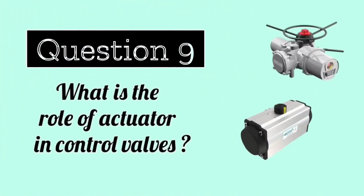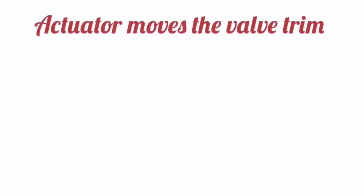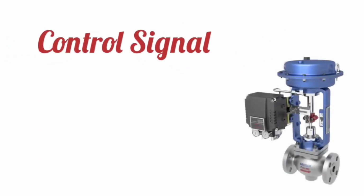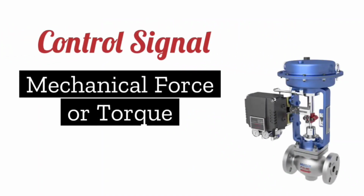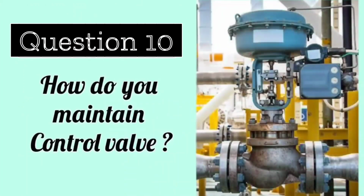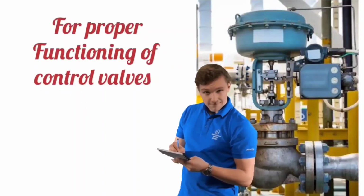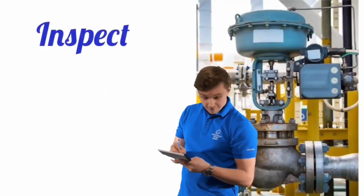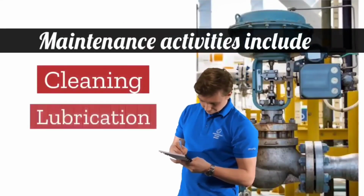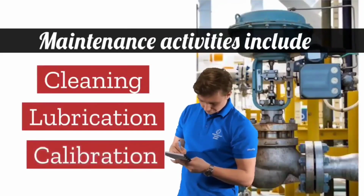Let's take the next question. What is the role of the actuator in a control valve? The actuator moves the valve trim according to the control signal. It converts the control signal into mechanical force or torque to position the valve according to the desired process conditions. Let's take the next question. How do you maintain control valves? For proper functioning of control valves, they are regularly inspected and maintained. Maintenance activities include cleaning, lubrication, and calibration of its position.